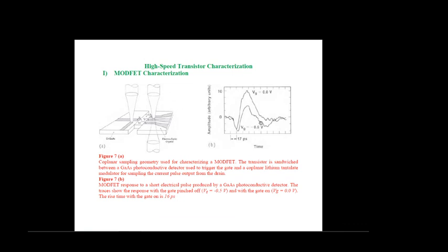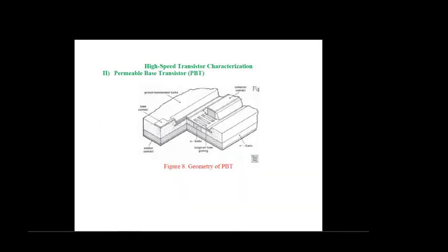From the characteristic curve, we can understand the improvement of sampling schemes discussed here. In another application, we use the electro-optic sampling technique with femtosecond, picosecond electro-optic signals for characterization of a PBT, that is a permeable base transistor.